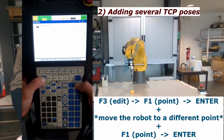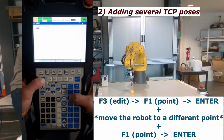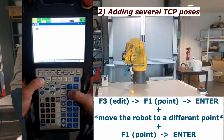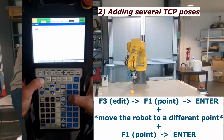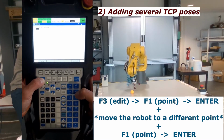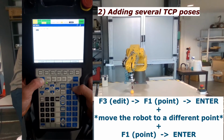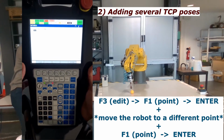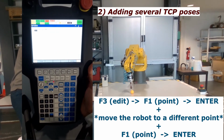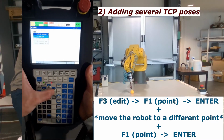Using the blue keys to move the robot, I will choose a position near to the ping pong ball as the second position to be recorded in our program. Now that I feel that I am close enough to the orange ball, I will save this position. Once again, by pressing the F1 key and then enter, this will be saved as the second position.